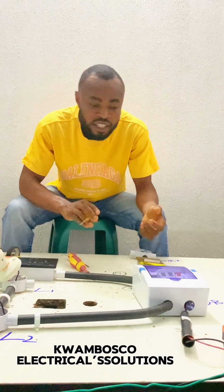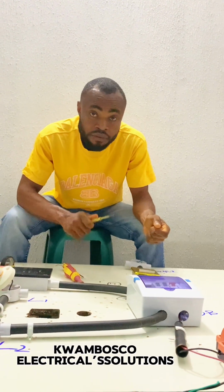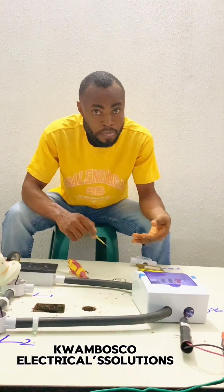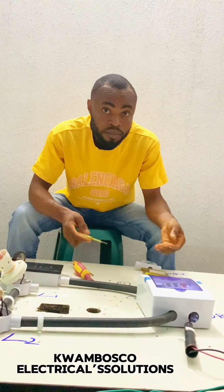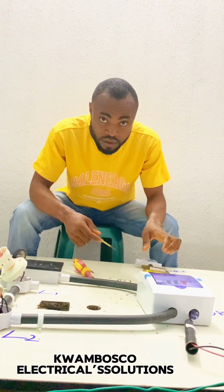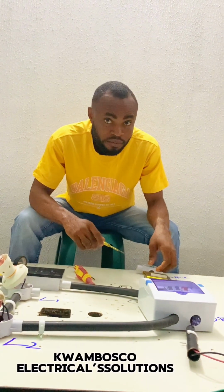Secondly, most times you don't tighten your earthing cable very well, so that earthing cable may eventually touch a live wire and it will cause this. Also, most of the circuit breakers are not good. The circuit breaker is supposed to trip off automatically, but sometimes the circuit breakers are poor. That's why the thing did not trip off.